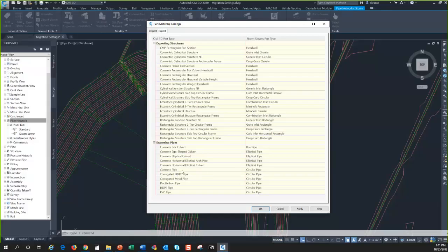It's going to be your predominant pipe, and then when your model is changed and the sizes and inverts are what you want, that's the time to go back through and change the pipe type in Civil 3D so that the labels and everything show up the way you want visually. If you try to take that all into storm sewers differentiated by type, when it comes back, it's going to change back to just one type anyway, so it's just not worth the effort.